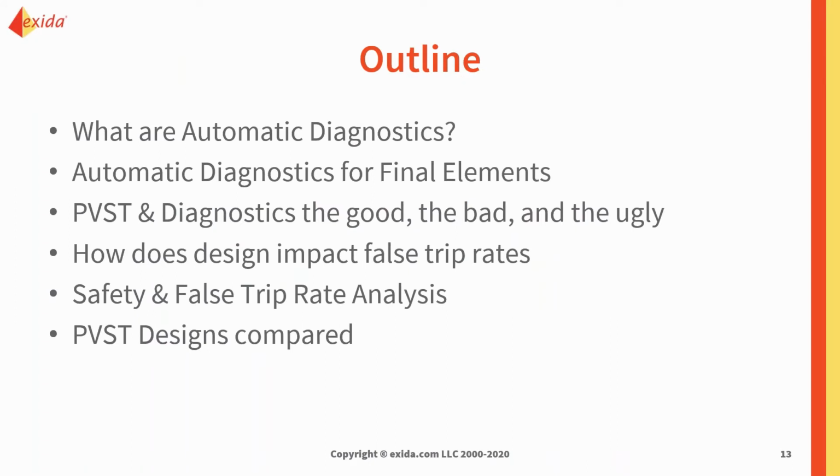So we're going to talk about automatic diagnostics and why they're beneficial. We're going to talk about those automatic diagnostics and why we might want to implement them on final elements. We'll talk about partial valve stroke testing and diagnostics, and we'll go through the good, the bad, and the ugly. And we'll take a look at how the designs impact false trip rates.